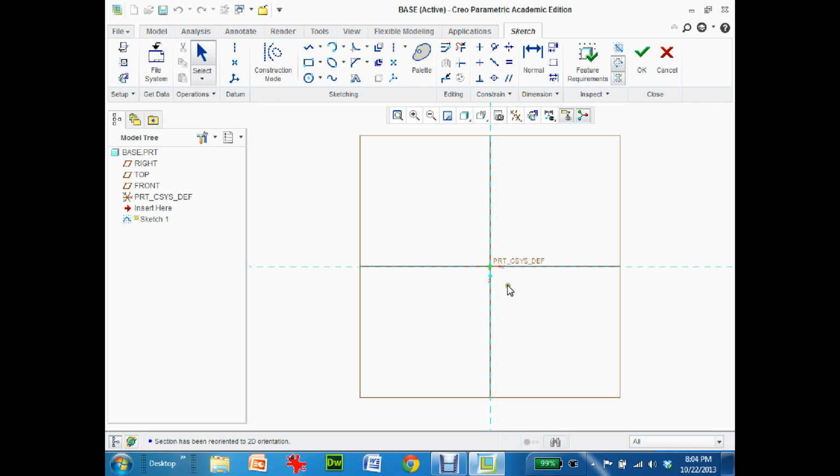So now that I have it in 2D, I'm going to draw my basic box. So I'm going to come up to here to the rectangle tool. I'm going to click on the little arrow and go to Center Rectangle. And then if you notice, I can actually click on these reference lines. That actually snaps to it, or clicks on it, puts a little circle there. It's maybe hard to see. Okay, so I'm going to click Dead Center, and I'm going to grab my rectangle, and I'm just going to draw it any size. Doesn't really matter, as long as it's a rectangle like this.